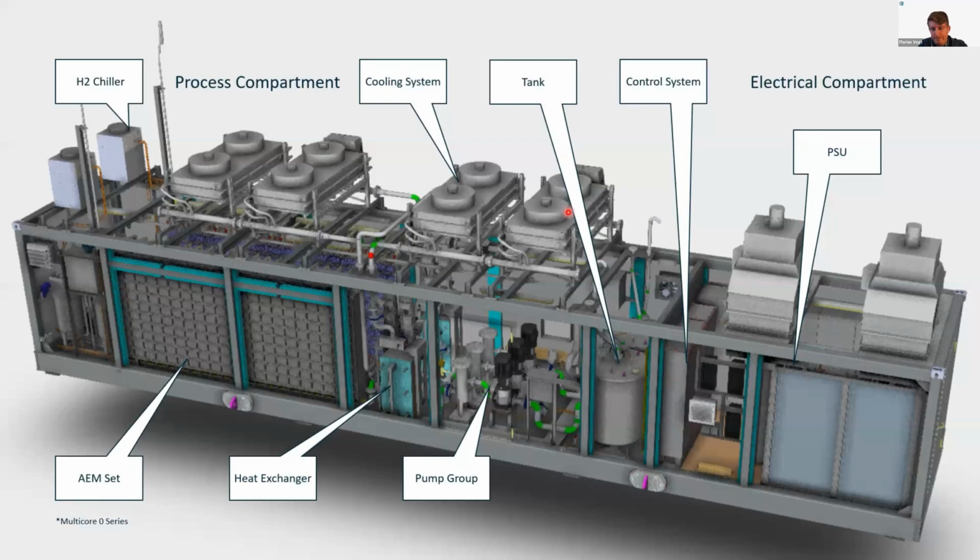Ready for another one? Yeah. Okay, so talking about the heat in the container, is it planned that the customer can use the heat that you have in your heat exchangers? Yes, this is planned, and we actually do it for our first customers. So we exchange the heat from the coolers with an additional heat exchanger, and then you can use the heat. You can bring it to a heat pump. You can heat your plant or whatever you want. This is possible. But it is expected that you need more design work for it. But this is what we do for our first commercial series, by the way. Okay, even a step further, cool.